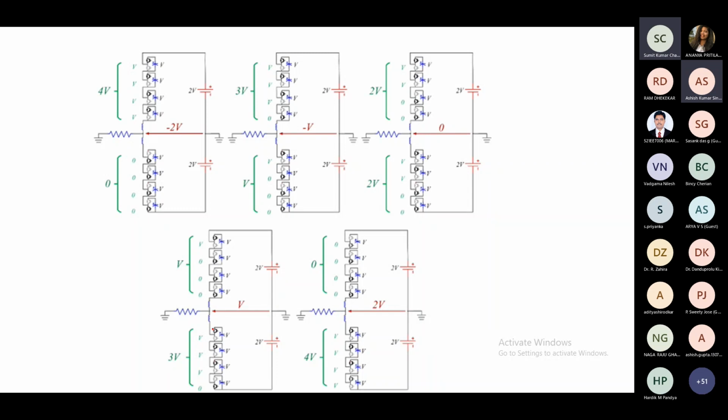So, of course, there will be an option here to get voltage levels 0.5V, 1.5V, etc. Sorry, not 2.5; that's beyond the range. This is by using the arm inductor as a potential divider, where the sum of upper arm voltage and lower arm voltage will differ from this DC link voltage by an amount of V.